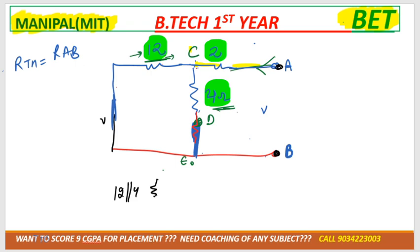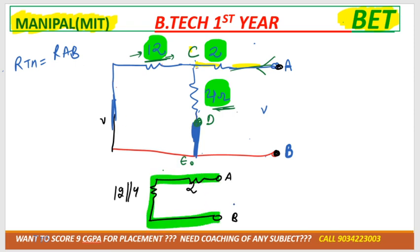12 parallel 4 combined into a single resistance. Okay, 2 ohm as it is. Again think of it like that. Now you can meet both of your friends, right? If they are on the same path, that means they are in series. So 12 parallel 4 is 12 into 4 divided by 12 plus 4, plus 2. That would be equal to RTH. Okay? Where will you always start from? From the friend who is farthest away. Okay?